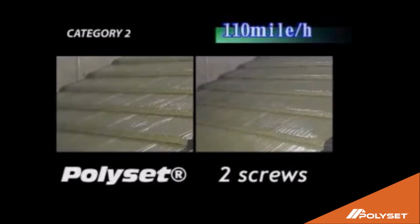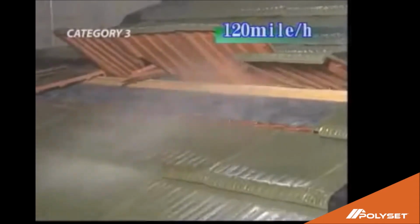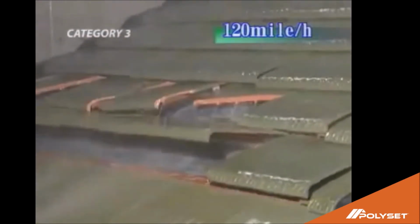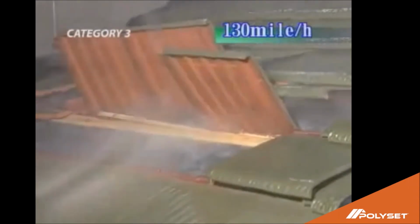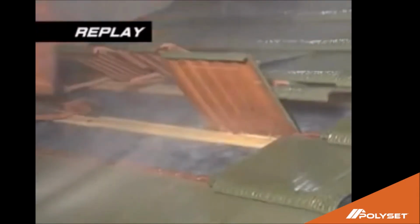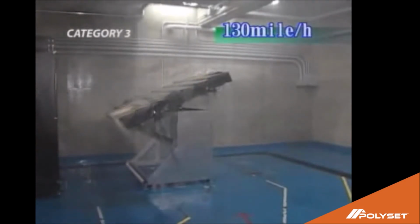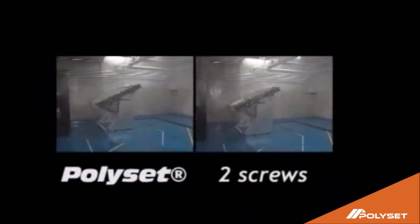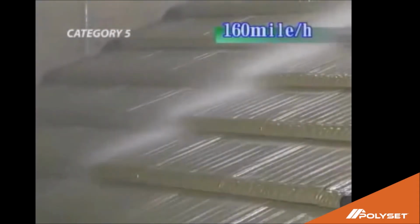In this video, you can see on the left side, those tiles are installed with foam underneath each and every single tile. On the right side, those are installed with two screws over a batten system. And you can see once the hurricane force winds get to at least a category 3, you start to see what's called chattering of these tiles and the airborne debris that's happening, the breakage. On the other side of the video, the foam down system, each and every tile acts like an individual system, meaning that if one of those tiles were to break, in the next wind event going underneath those tiles, most likely those are going to stay secure because they're individual systems, versus if they were mechanically fastened, wind gets underneath those tiles and you start to get that piano, that breakage, that chattering type effect.